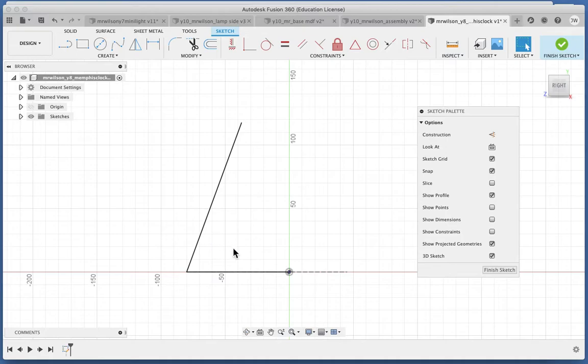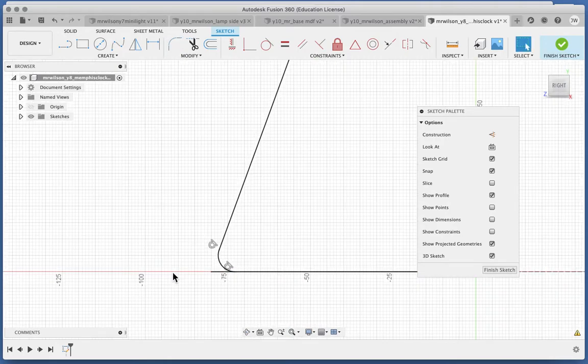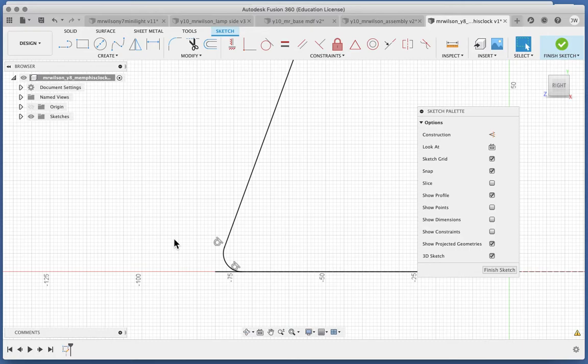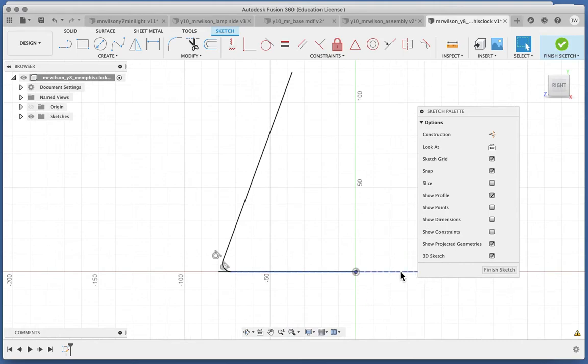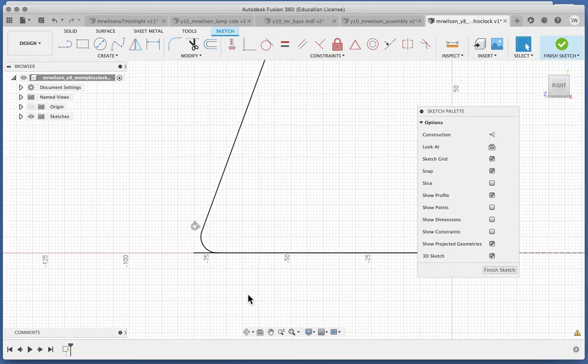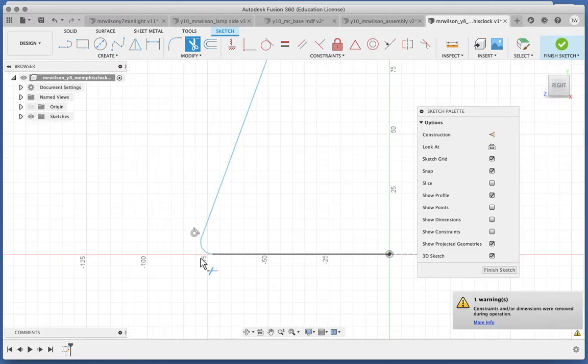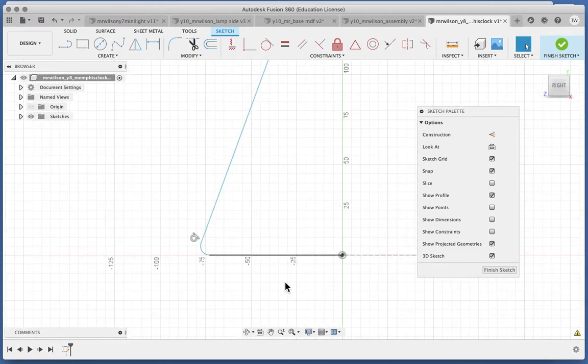Before we create the thickness of the acrylic, we're going to change this very sharp connection down at this point here for something a lot softer. So I'm going to put in, say, 30. Sorry, I'm going to put in 5. It was 30, I'm going to reduce that to 5 and press enter. And we've now got a nice smooth shape here. If you end up with a little piece sticking off the bottom like that, then I wonder if we can just trim that out using our trim tool. Yeah, we can go ahead and trim that. Okay, so T for trim.